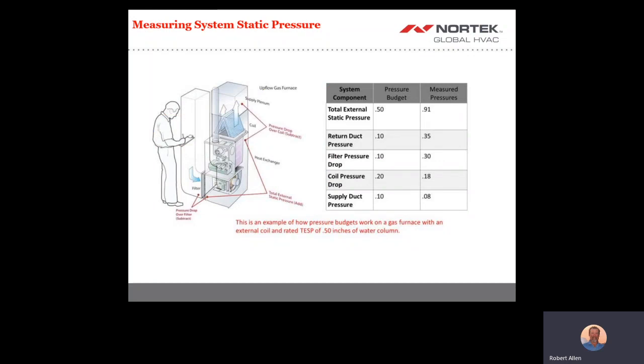This spring, with the majority of people having to stay home due to COVID-19 and with the cooling season fast approaching us, our industry will surely start receiving those calls of inadequate or failed air conditioning. To increase your value to the consumers and to put more profits in your pockets, we suggest diagnosing the entire HVAC system, remembering that airflow is the most critical component in your diagnosis, and that we should always test airflow first before hooking up your gauges and hoses to that outdoor unit.